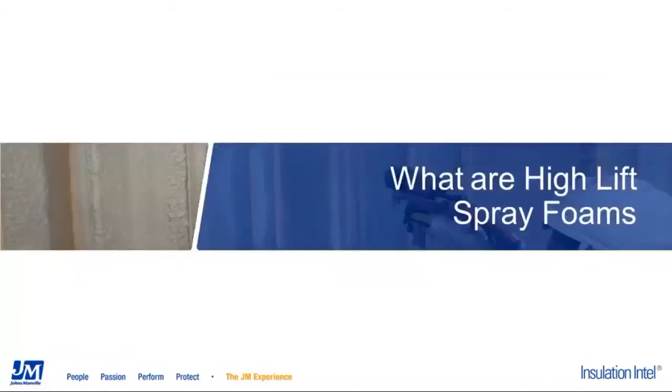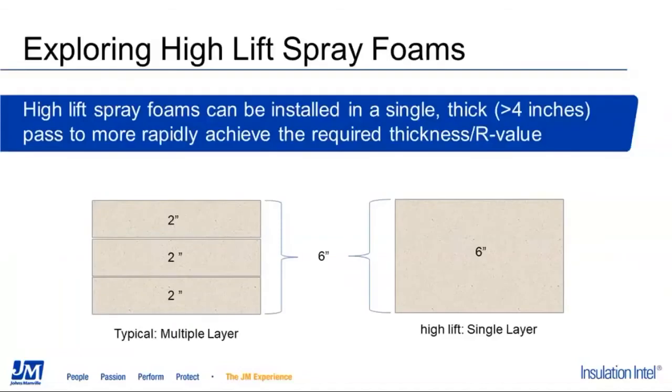So now that we know what the properties of spray foam are and some application considerations, what are high-lift spray foams? High-lift closed-cell spray foams are becoming more and more popular in the industry. They are distinct from traditional foams in that they may be sprayed in one single pass from 4 inches up to over 6 inches, rather than in multiple passes with the waiting period in between to achieve the same total thickness.